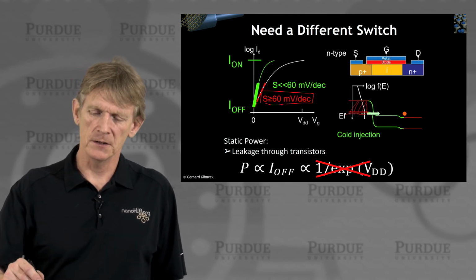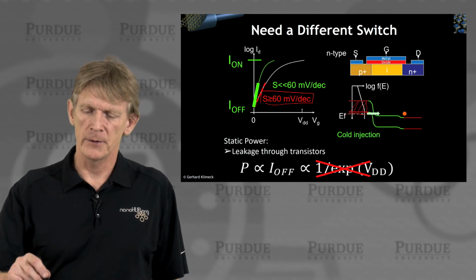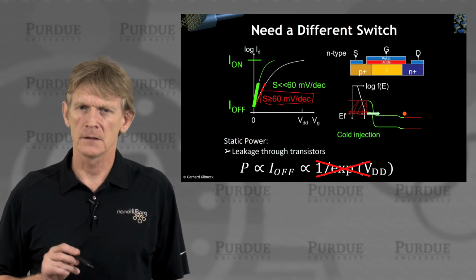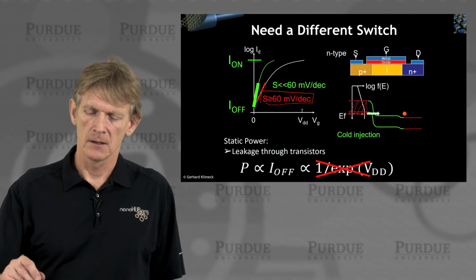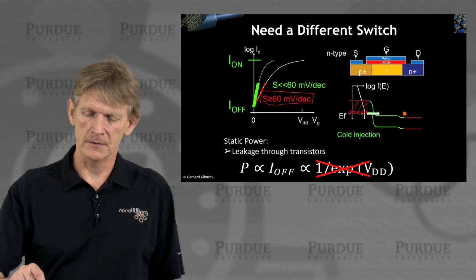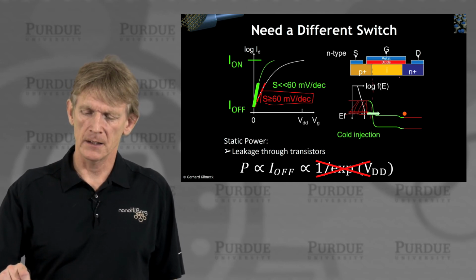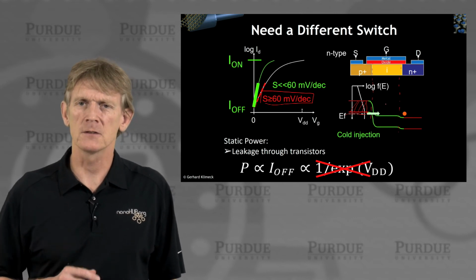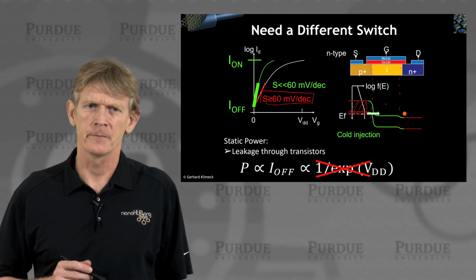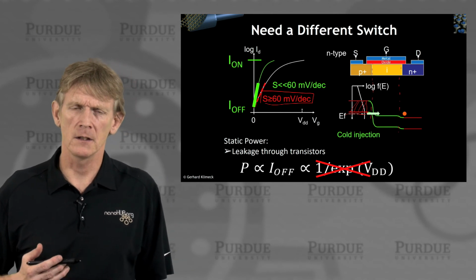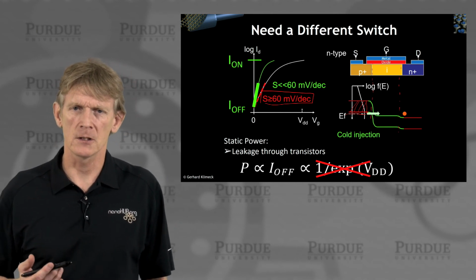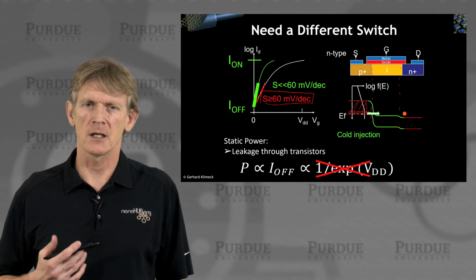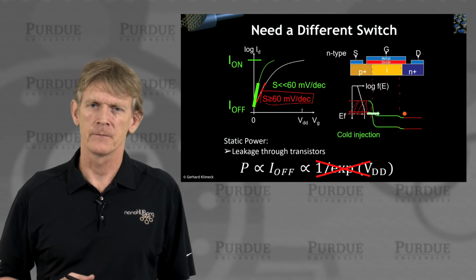So what this is here really a PIN junction in the simplest of all sketches, where you have, here's the junction translated down, here's the next junction translated down, and you have a gate that pushes this potential up and down. So your barrier material is somewhat independent of temperature, but it's truly shutting off the density of states.